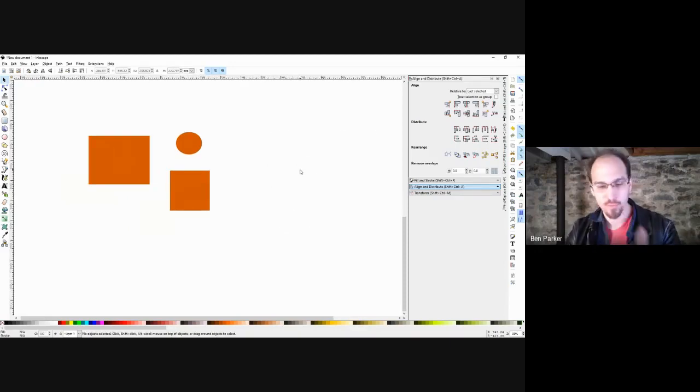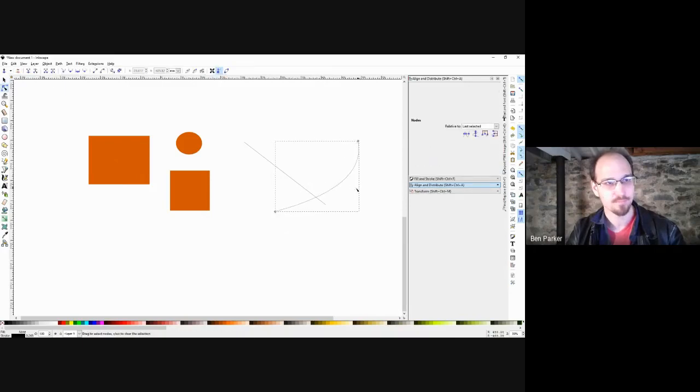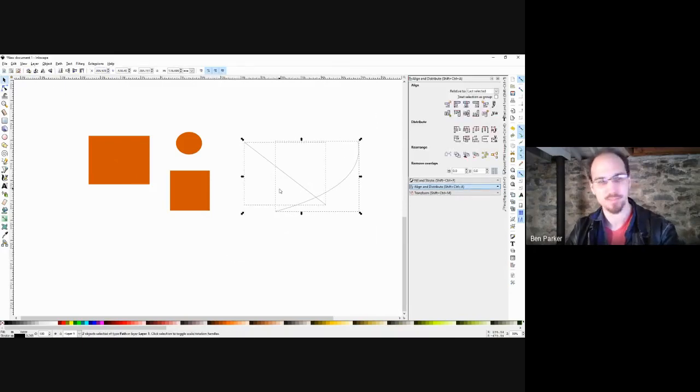By the way, the way to draw the line is with this button. So I showed you how to use Bezier curves before. The draw freehand lines, similar thing. It's just 2 points, or you can press F6, and it has the same abilities as the Bezier curves.